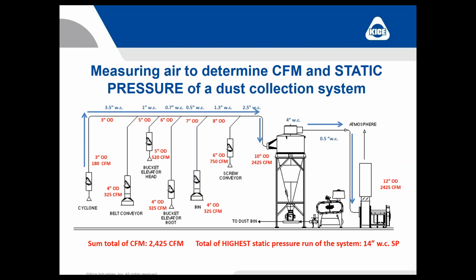But back to the red, I sum total all of the pickup points. 180 from the cyclone on the far left, 325 from the belt conveyor, 520 from the head, 325 from the boot. All those total up to 2,425 CFM.